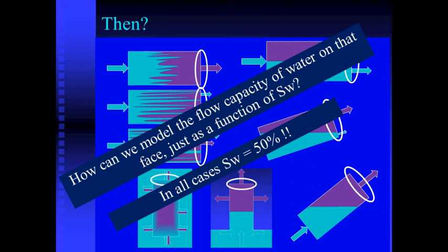Based on this simple analysis, describing multiphase flow only in terms of water saturation seems like an impossible task. It is evident that there are other variables that also impact the movement of fluids. However, an initial answer is given to this general question, the one that somehow triggered the concept and use of the relative permeability curves in reservoir engineering.